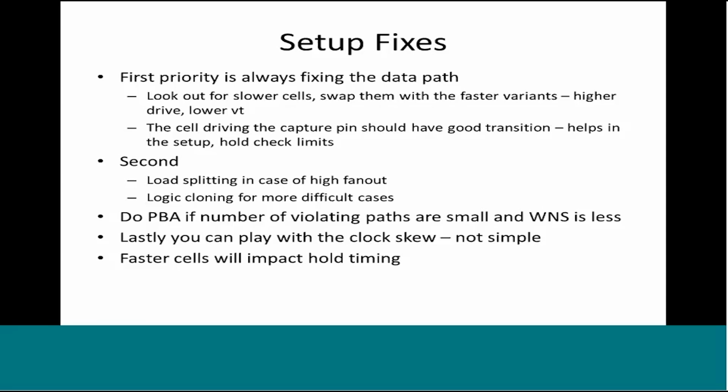Next, this technique is slightly more advanced. You will understand this with some experience maybe. Let's say a buffer in the data path has maximum drive strength, and it is driving, let's say, 50 or 20 nets. Now you cannot upsize this because it is at maximum drive strength. When I say upsizing, it means that a buffer should be replaced only by a buffer. It cannot be replaced by some other element, because you have to maintain logical equivalency. So upsizing means the logic function remains the same, only the drive or the VT type changes.